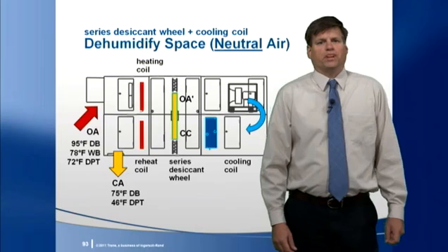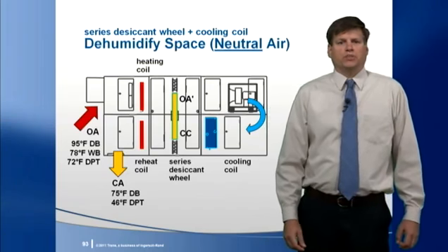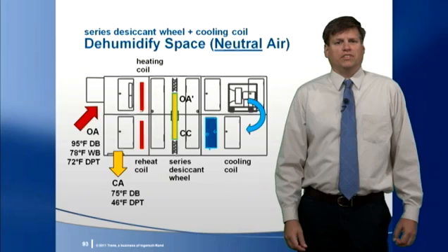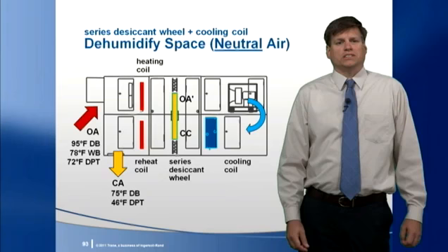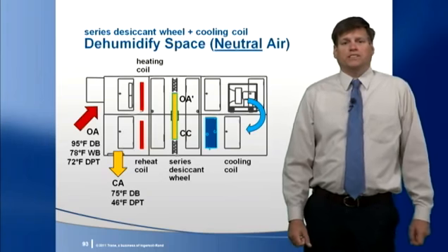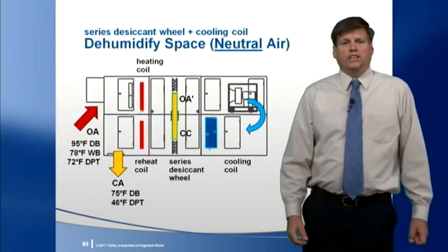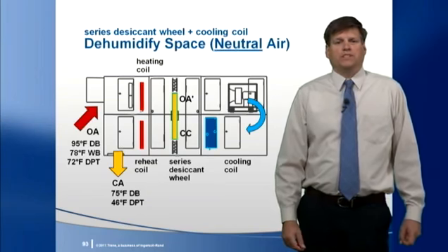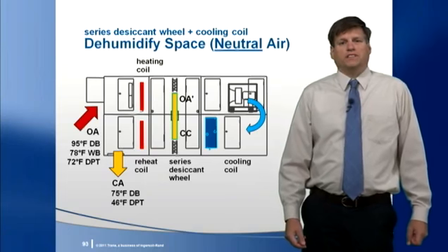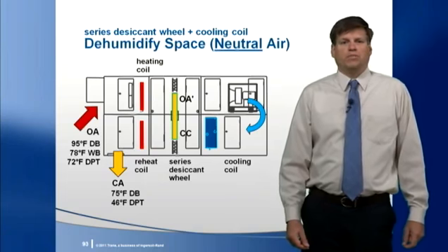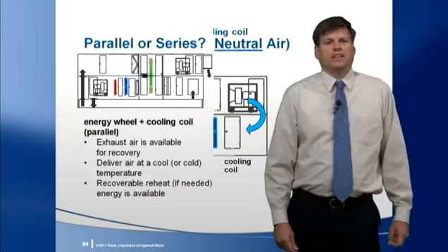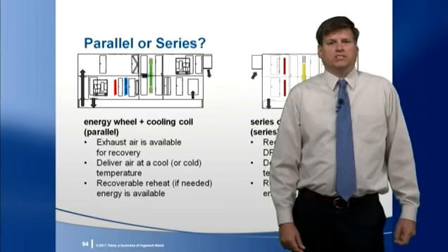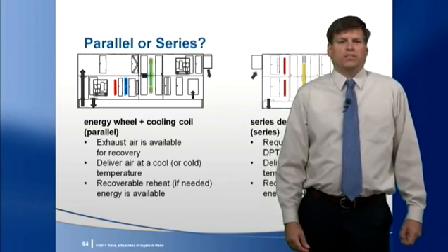The main driver in this desiccant process is the difference between the outdoor air relative humidity and the relative humidity of the air leaving the cooling coil. At the example condition I showed, the outdoor RH is low enough to regenerate the desiccant. But when the RH of the entering outdoor air gets high, like on a mild rainy day, preheat will likely be needed to lower the relative humidity of the incoming air. As Paul mentioned, if the dedicated outdoor air system delivers only the minimum ventilation air required, this preheat is allowed by ASHRAE 90.1.